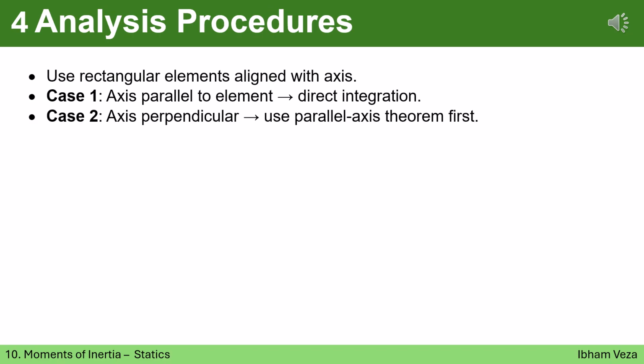Analysis procedures. When evaluating moments of inertia through integration, the choice of differential element is important. We generally use rectangular strips aligned with the axis of interest. If the strip is parallel to the axis, direct integration is usually straightforward. If the strip is perpendicular to the axis, it is often more efficient to use the parallel axis theorem before integrating. Selecting the appropriate method can significantly reduce computational effort.